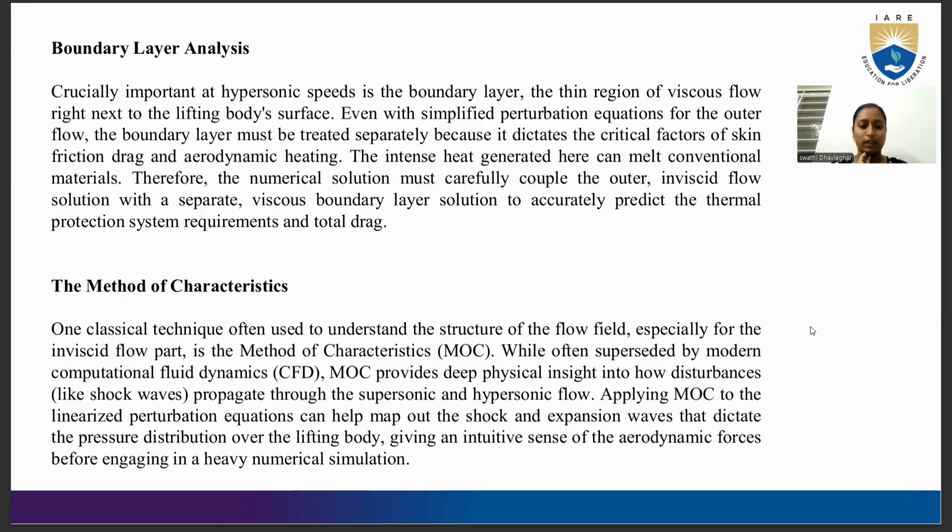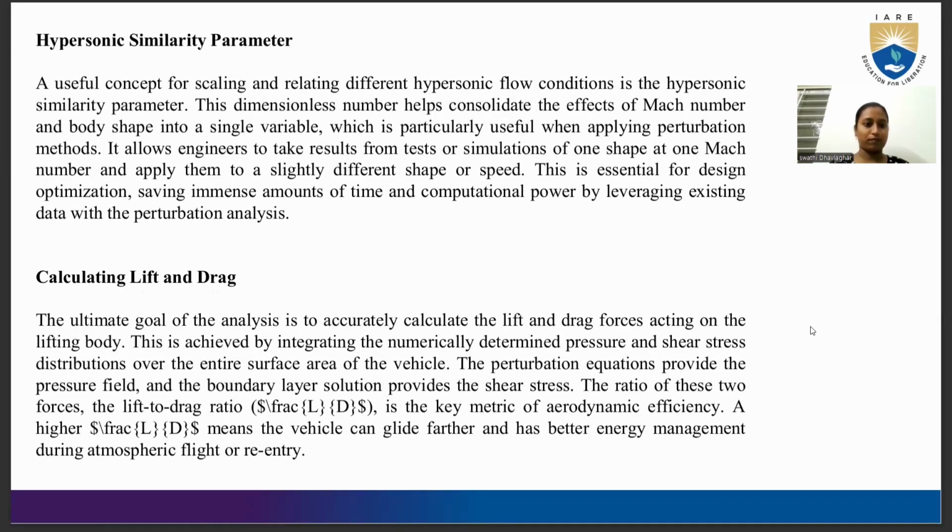Applying MOC to the linearized perturbation equation can help map out the shock and expansion waves that dictate the pressure distribution over a lifting body, giving intuitive senses for the aerodynamic forces before engaging in heavy numerical solutions.